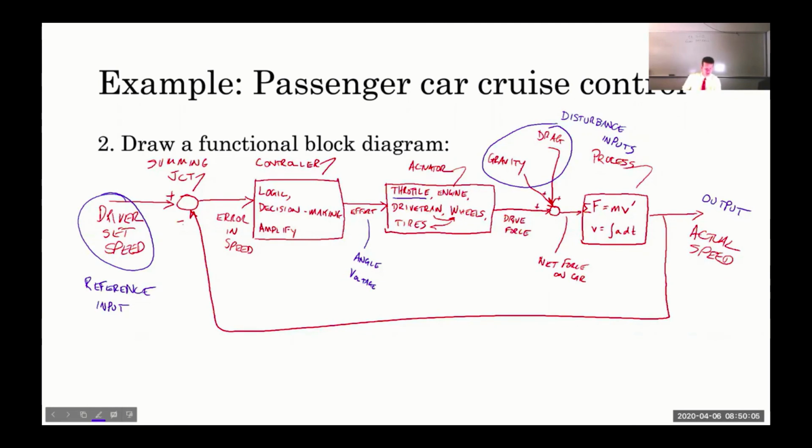Now, what you've hit on here is actually a major shortcoming of the cruise control example as your first control system. We aren't talking about brakes. We're just talking about the engine. So that is a gross simplification, but honestly, one that most cruise controls nowadays use, right? Your cruise control in your car, unless it's a pretty fancy car, doesn't touch the brake pedal. It just opens or closes the throttle to adjust your speed, and it relies on the drag to slow the car down. I didn't catch your name, which is going to make it hard to record your participation.